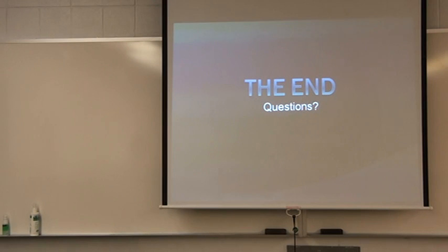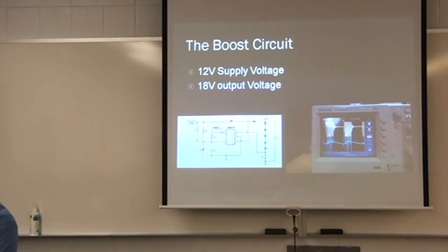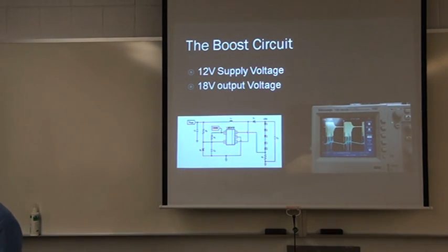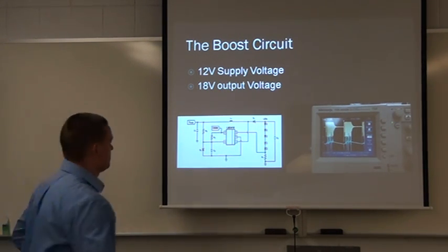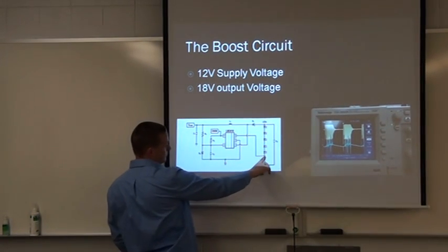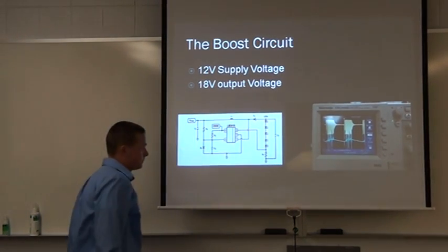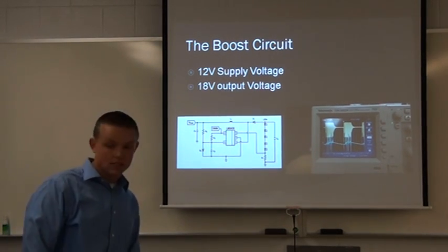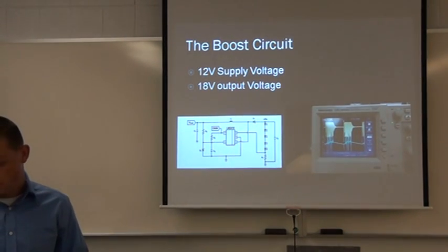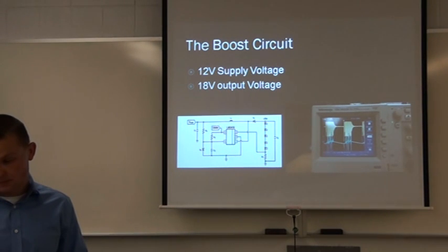So, can you go back 2 slides? On this one, you said the lower pattern was across the capacitor. Did you mean the lower resistor there? The blue waveform? Yes. So can you point to the resistors so we can know where it is? That's essentially measuring the current through the LEDs, right? Yes. And that's what's used for the feedback. To maintain that current, okay?